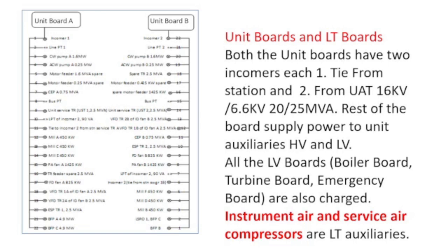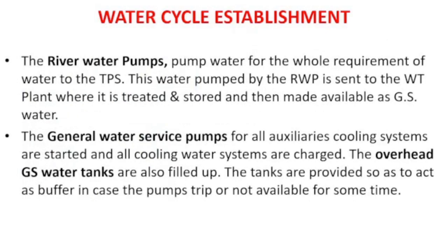All the LV boards, low voltage boards, that is boiler board, turbine board, emergency board, they are also charged. Instrument air and service air compressors are LT auxiliaries so that they can be run after the charging of LT boards. Then the water cycle establishment.